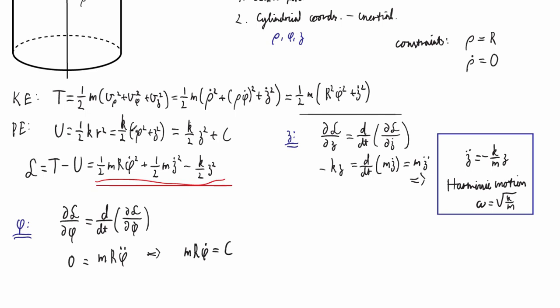There's actually a problem. You can see that here because the unit isn't right. Every term here is supposed to have the unit of energy. So mass times velocity squared, that's the unit of energy. Here is mass times velocity. So we have meters per second, but it should be meters squared per second squared, so there's something wrong there. So we see we've actually forgotten the square over there. So it's m R squared times phi dot squared. Okay. So that's what we get there.